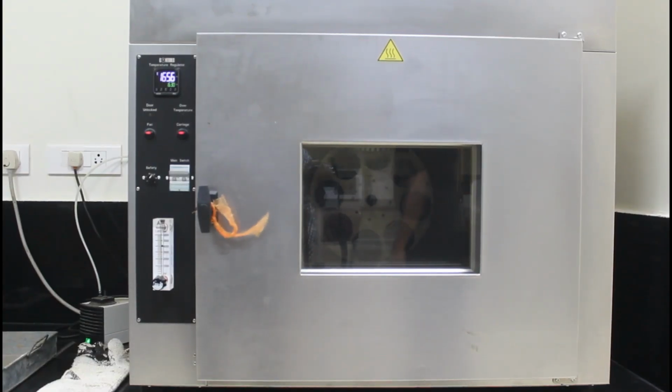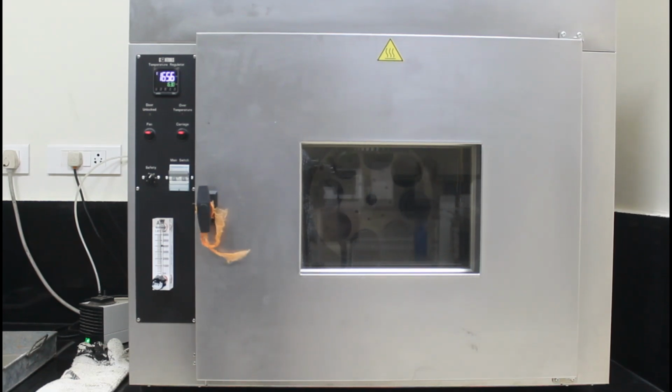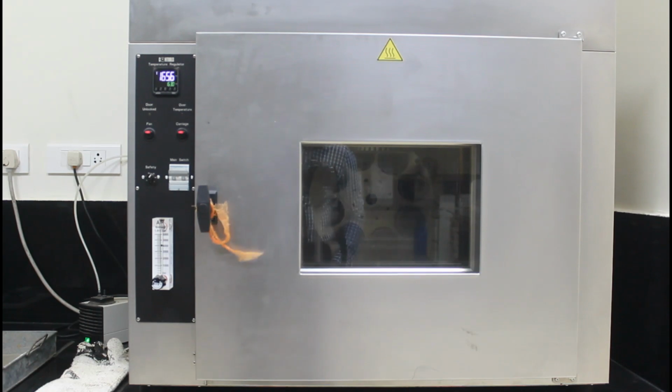So now we have completed 85 minutes, right? So now we will stop the oven, and we have kept two bottles for each binder. One is to determine the mass loss, where we will determine how much mass has been lost due to the aging effect, and the other set of bitumen will be used to do a rheological test to compare the properties of aged and unaged binder in short-term condition.